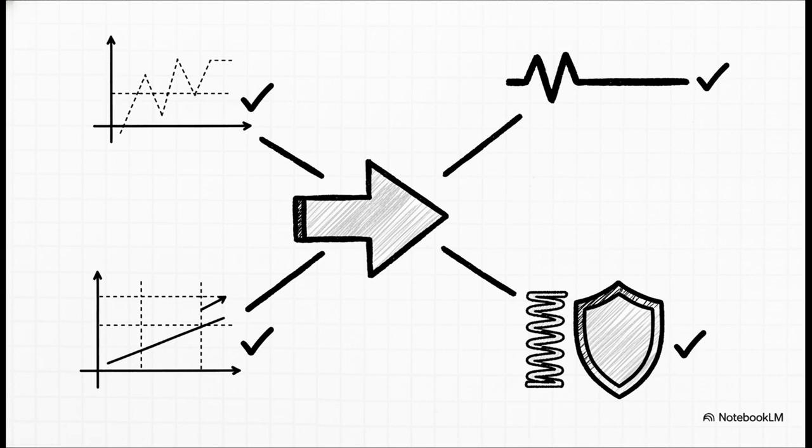It makes the whole system more stable. It fights back against that wind-up problem from the integral part, and it helps the system lock onto its target much, much faster. But the real art is in what's called tuning the controller, finding the perfect balance between P, I, and D. Too much P makes it jerky, too much I causes that overshoot, and too much D can make it oversensitive to noise. Getting that balance just right is what separates a good control system from a great one.